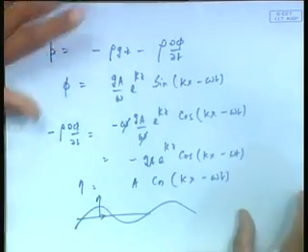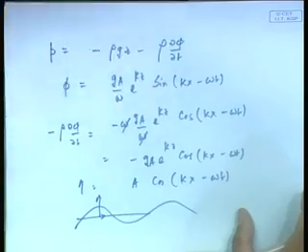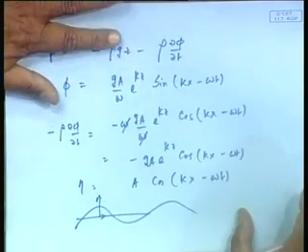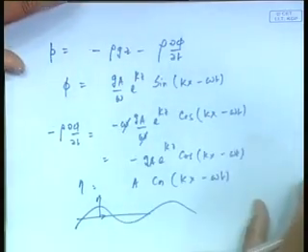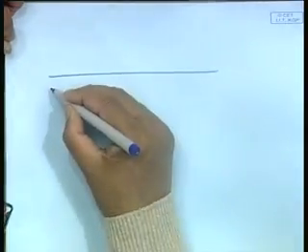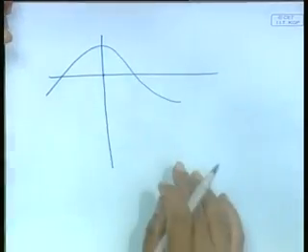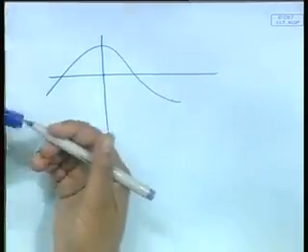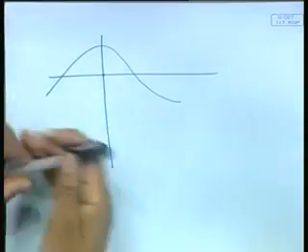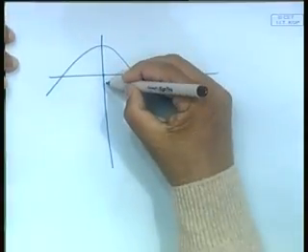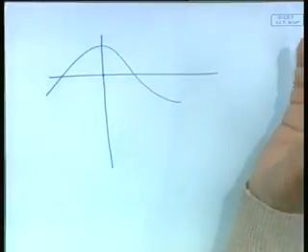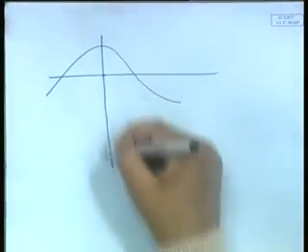Okay. Now, let us look at the two parts of the pressure by a plot, the hydrostatic pressure and the linear dynamic pressure. Now, let us look under the trough. Remember, this is Z0. How does the hydrostatic pressure vary? Well, it is minus rho g z, okay. Z is negative down.